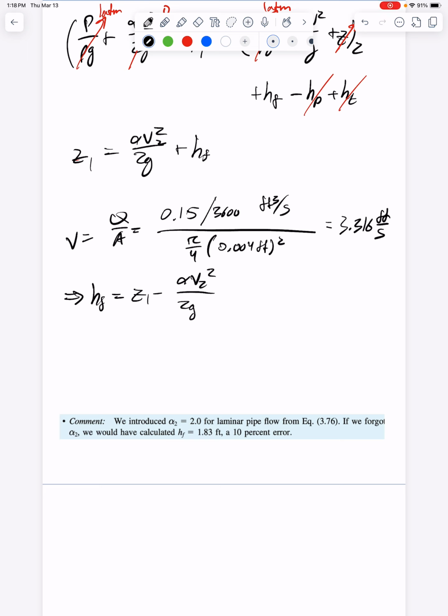There is Poiseuille flow, and that's the parabolic profile. Therefore, the centerline velocity is going to enter first before the other velocities of that system. So when you take the average of the velocity, that's the V term, but we also need to apply the kinetic correction factor. For laminar flow, alpha will be equal to 2. For turbulent flow, alpha is roughly 1. Remember earlier, we made the assumption that our flow is laminar. Therefore, alpha is equal to 2. Just something to keep in mind.